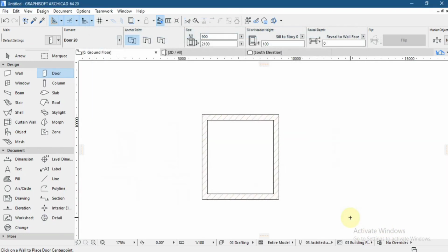Okay, we're done. Now it's time for me to place the door. If you go here, you notice that there's a black line in front. And this black line is where you want the door to start from. I'm going to explain. You've noticed that in some buildings, like the external doors, if it's an entry door, it's usually flush inside and recessed outside. I don't know if you understand what I mean, but let me show you with this tool.